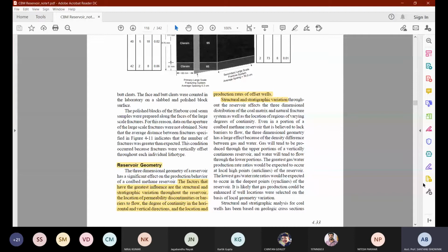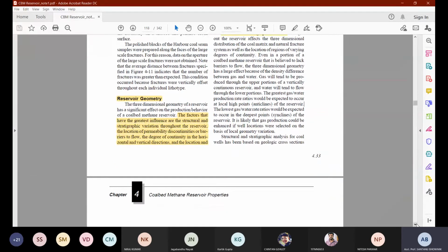Whenever you visualize this type of thing, you will be able to understand how this borehole drilling is also going to generate some fractures, which are the induced fractures. And for this, some of the earlier existing fractures can be interconnected, they can be overlapped, or they can be extended. Their aperture can be extended, and so the directional variation of the permeability or the porosity obviously is going to change. So again, depending on this, the differences in the flow properties, in the porosity and the permeability, because these two are the main important parameters.